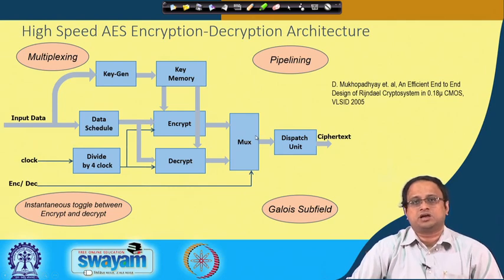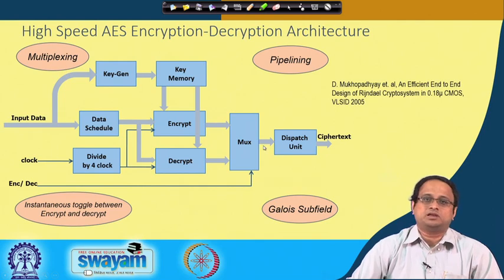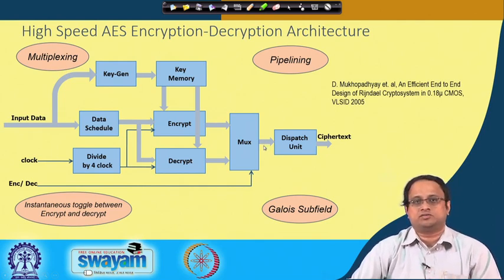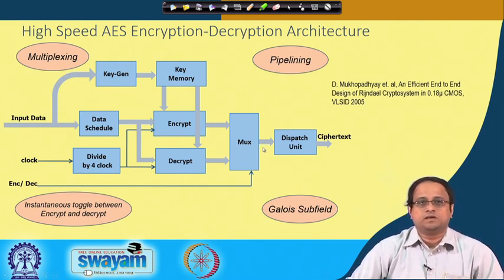On the other hand, there may be some modes of encryption where pipelining would give advantage. So that depends upon how you want to use your AES block cipher. You can choose to apply pipelining or not, but at the same time, when you apply pipelining, there is an increase in area, but also an advantage in terms of throughput.